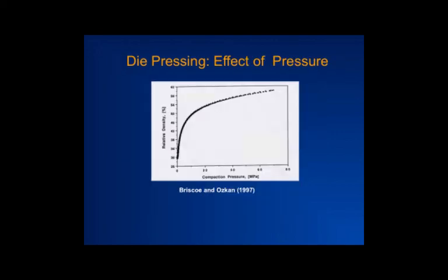So mainly what you have is you start out with loose powder, apparent density, right? And you begin to increase the compaction pressure, and slowly the compacted density increases. Initially the density increases rapidly. For an increase from 0 to 20, your density is almost doubled, but then to go from 20 to 40, you have just about a 10% change, right?